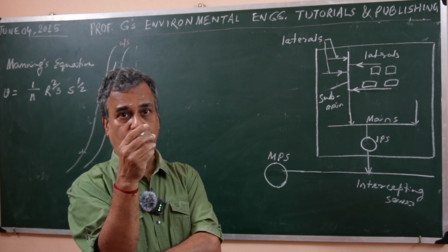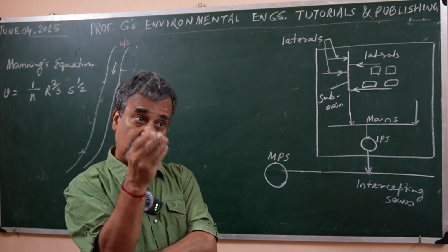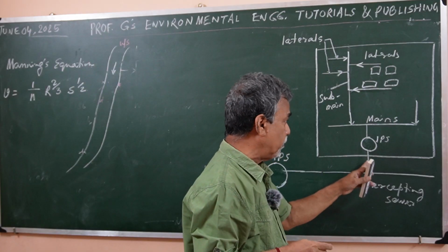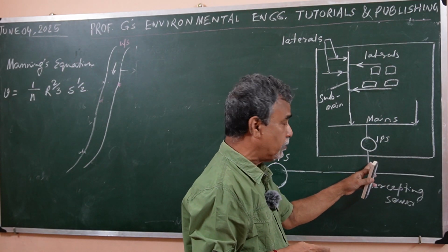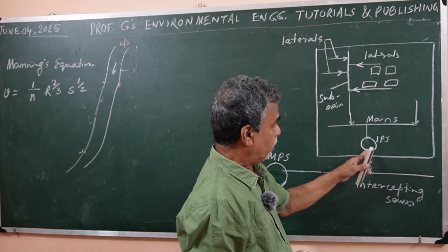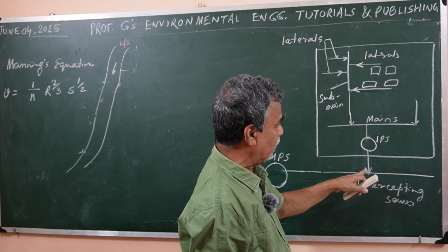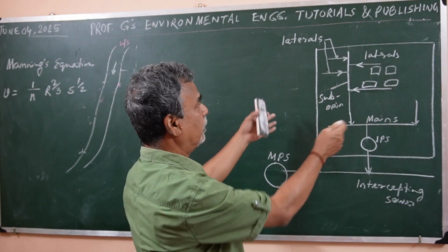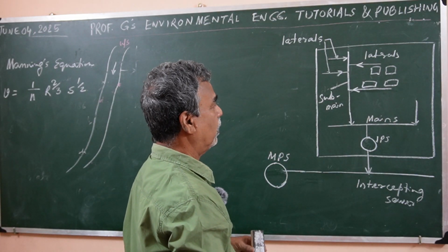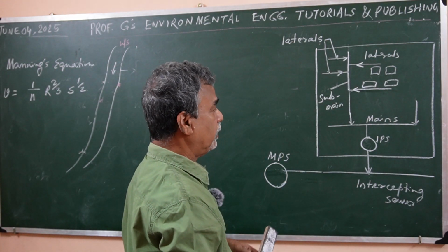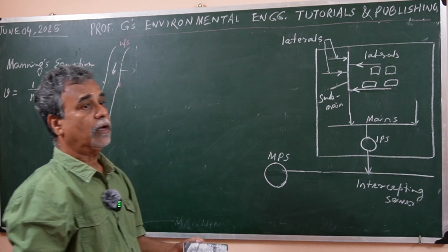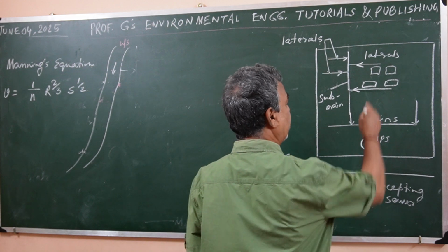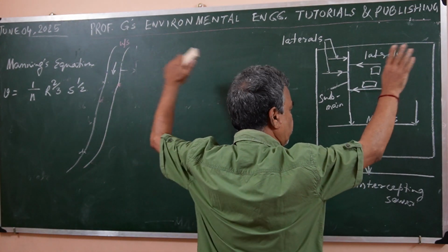It is not a pressure flow, normally, unless required. But when it is pumped, subsequent to pumping, it becomes pressure flow, right? But thereafter this will again be gravity flow, unlike a water supply system, where usually it is always under pressure, and this is pressure flow. So here intermediate pumping is not required.